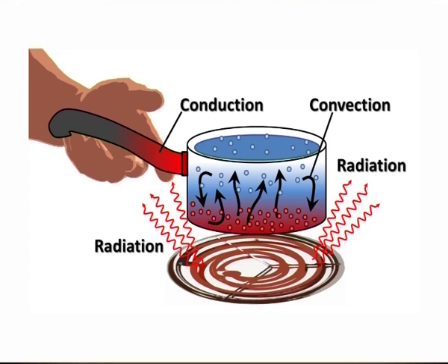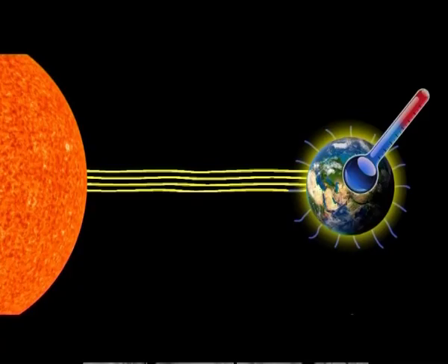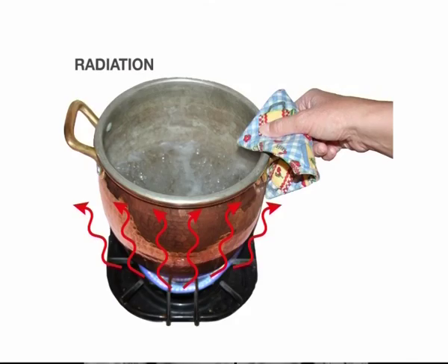Section 3.3: Radiation heat transfer. Radiation heat transfer occurs between two surfaces by the emission and later absorption of electromagnetic waves. In contrast to conduction and convection, radiation requires no physical medium for its propagation. It can even occur in a perfect vacuum, moving at the speed of light, as we experience every day with solar radiation. Liquids are strong absorbers of radiation. Gases are transparent to radiation, except that some gases absorb radiation of a particular wavelength. Solids are opaque to thermal radiation.